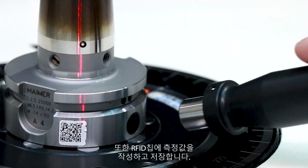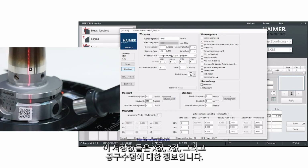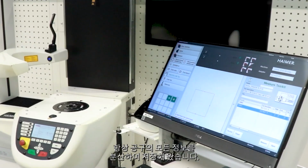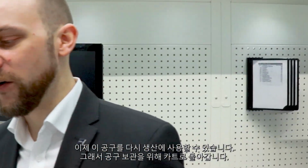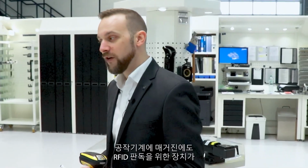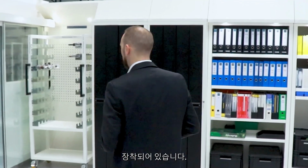And we are also writing the information on an RFID chip. That means X, Z values, and also the information about the tool life, so that we have always decentrally stored all the information on our tool. And now I make this tool again available for our production, and therefore we go back to the tool holder cart. And also on our machine tools, we have RFID reading units directly in the machine tool magazine.